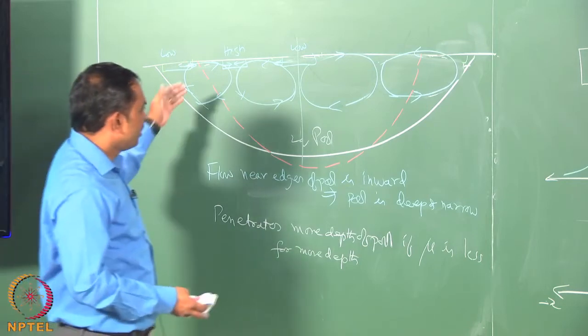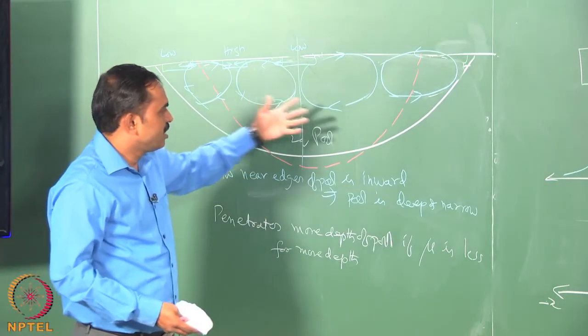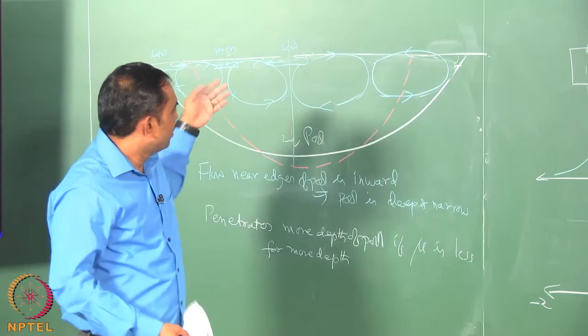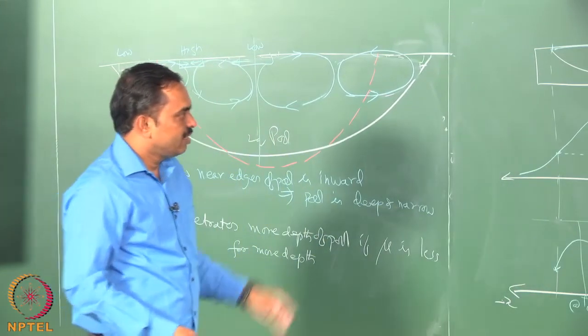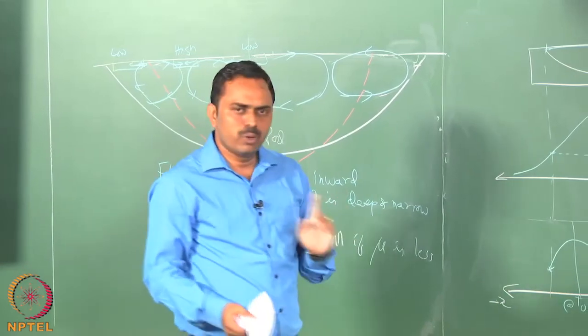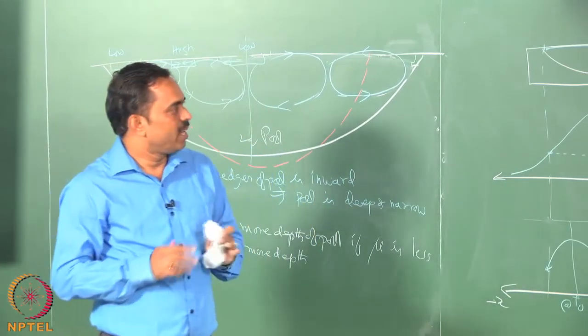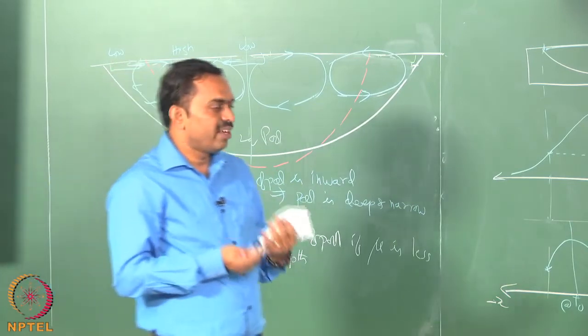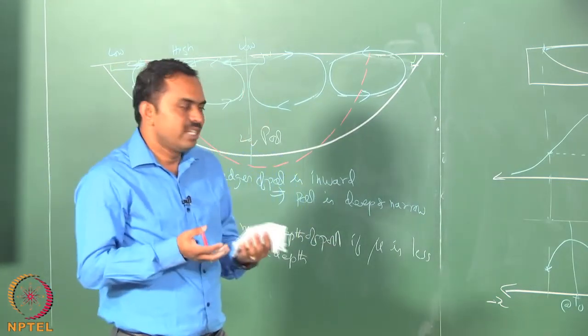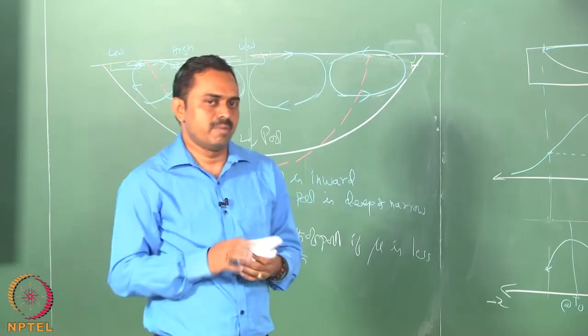So, this is how the surface tension is going to change the weld pool shape, and we can rationalize that from the surface tension variation. Solutal effects are not playing a role only from the surfactant elements, but also from the normal alloying elements, because alloying elements can, for example, change the surface tension in the case of dissimilar metals.